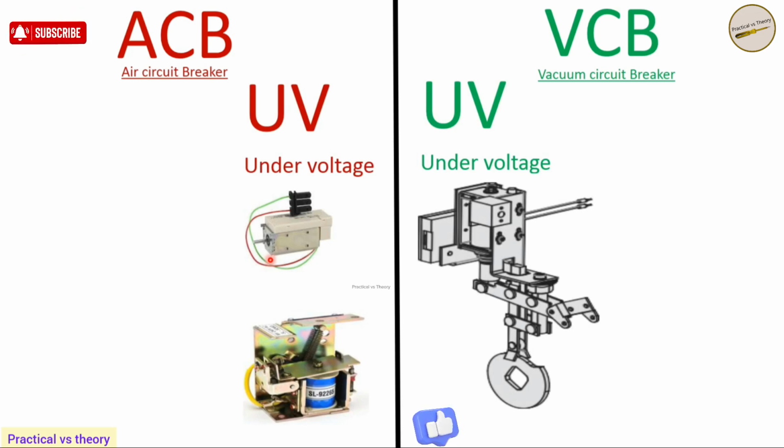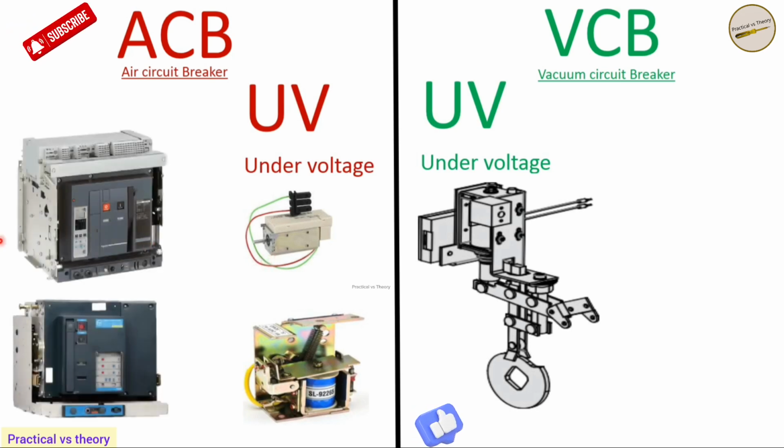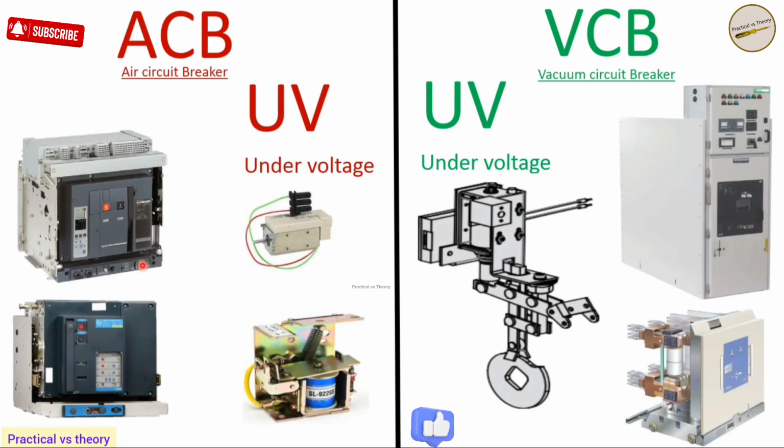If you want an undervoltage breaker, right? So, if you need an undervoltage breaker, you can also install an undervoltage release in a VCB. Now, that's settled. Does your ACB and VCB have undervoltage? Both have undervoltage. Now, what does undervoltage mean? Undervoltage means if the voltage drops or if there's no voltage, your breaker will trip, or it's used in interlocking for undervoltage. Let's move on.